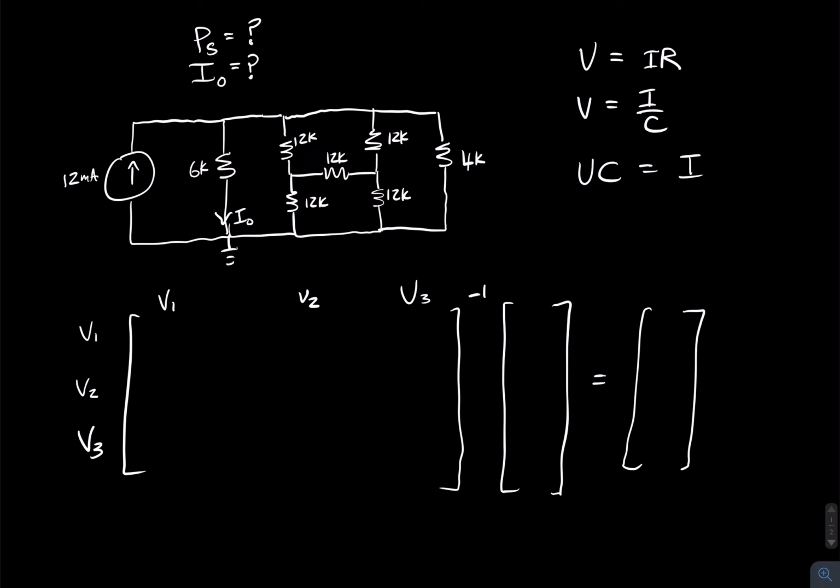But what we're going to actually do to make nodal analysis a little easier, first we're going to define the nodes. So we have this top guy. This is all one node, all the wires that are connected right here. This is all a node. And we'll call this guy V1.